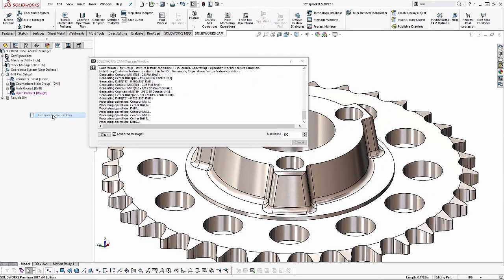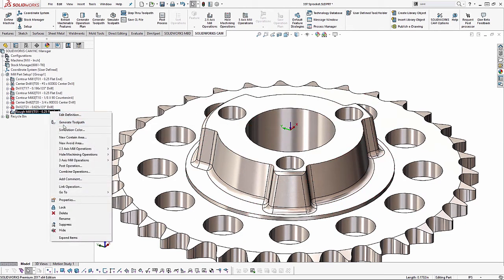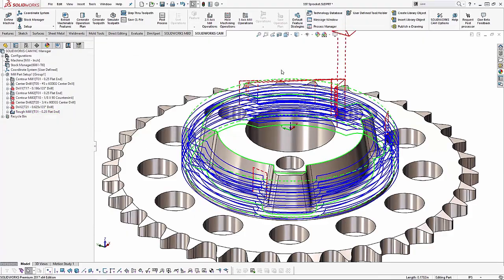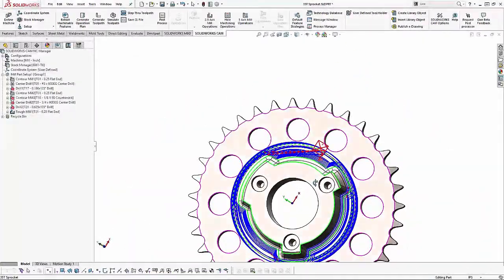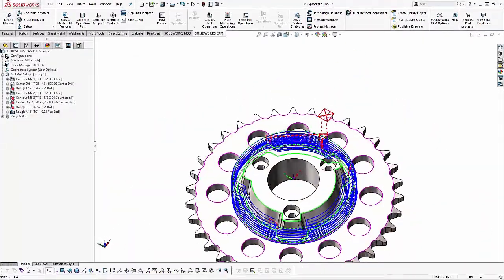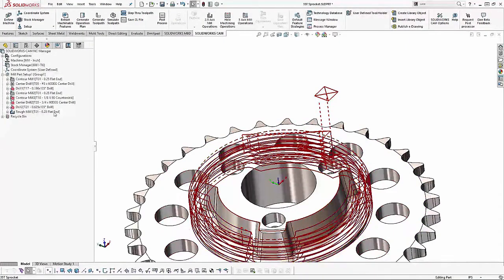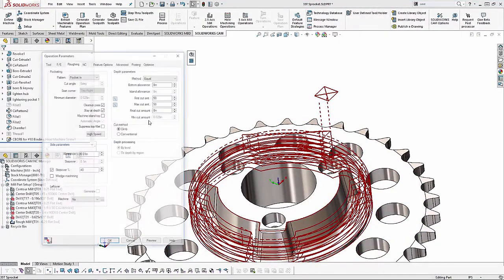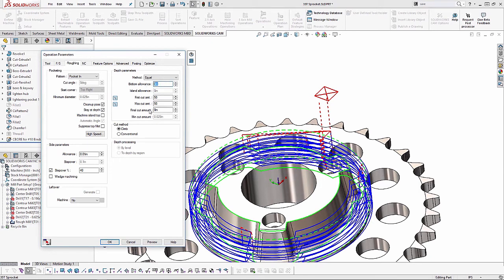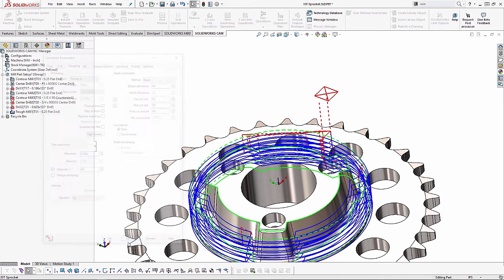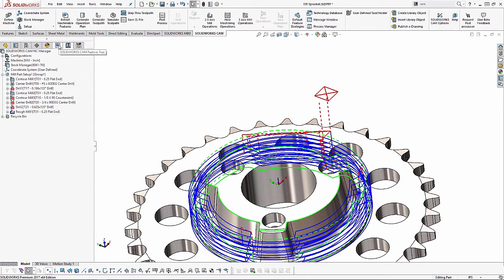We're going to go ahead and run that through the database. It will create a rough mill. We'll generate some toolpath, and there is our roughing pass around that area. Now, how rough is it? We can control that. We can tell it, leave 0 allowance on the bottom, so we are cutting to the bottom, and we are leaving 100 thousandths on the sidewalls. Totally customizable, but we're going to go ahead and just leave that there.